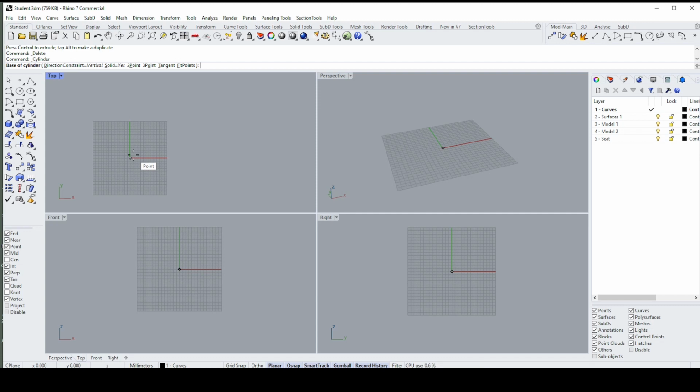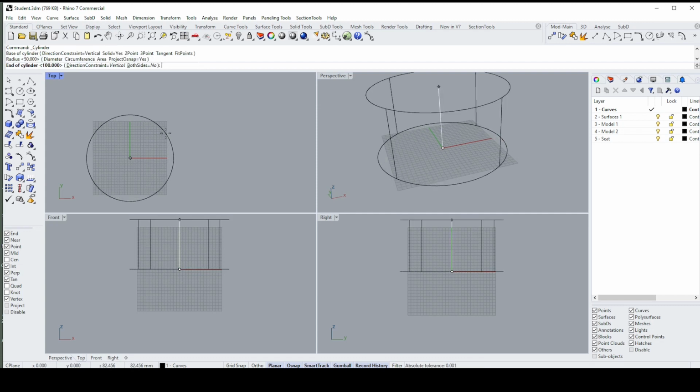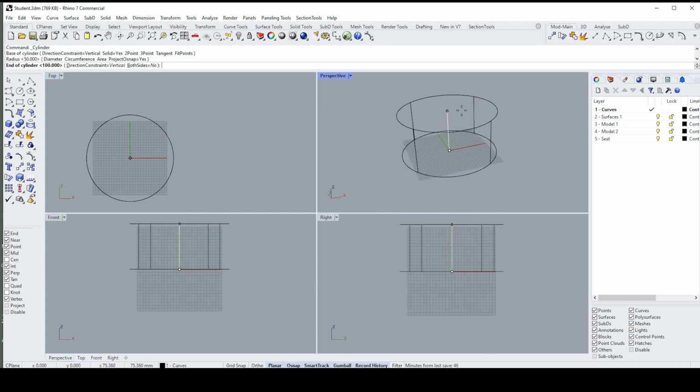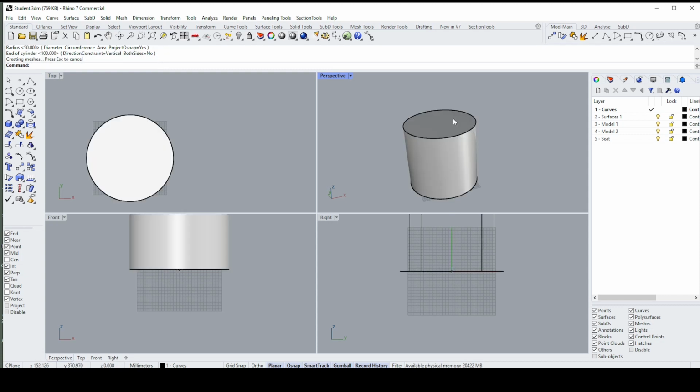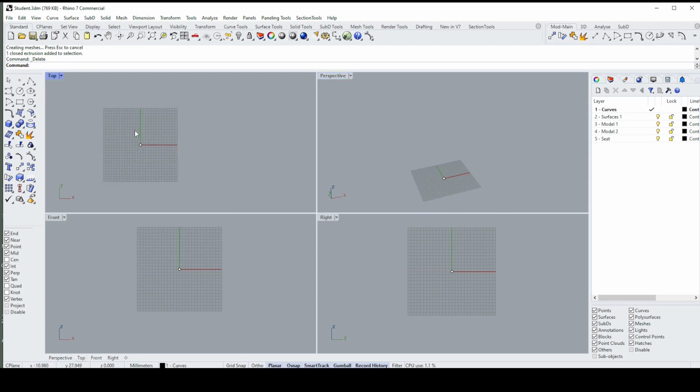I'm going to use it as the 0 point, which I've created a point at. And you just drag out, in this case, a circle, and then it'll immediately skip to the extrude tool, and you'll be able to extrude that circle into a solid. Another way of doing this kind of command, or of doing any command, is to actually input figures.